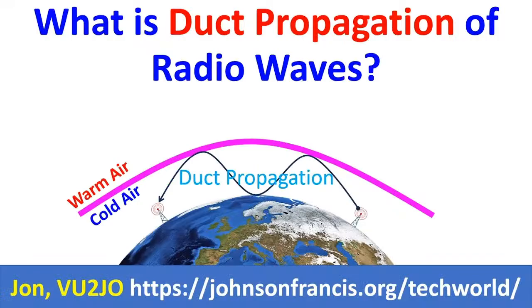Duct propagation is a special type of propagation around the curvature of the earth even as much as 1000 kilometers at VHF and UHF frequencies. This occurs when there is a temperature inversion in the troposphere. In temperature inversion in that region, the temperature increases with height instead of decreasing.